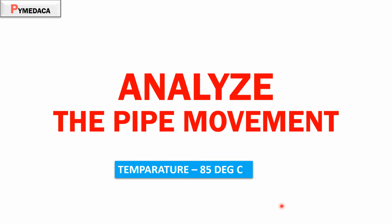So one of the primary factors for analyzing the pipe movement is the temperature. So let's consider the temperature of this line is 85 degrees Celsius. So at 85 degrees Celsius, what will be the pipe movement? As a piping design engineer, you have to be aware of it. You have to understand that the pipe will expand even at 1 degree, even at 2 degrees, and 3 degrees.